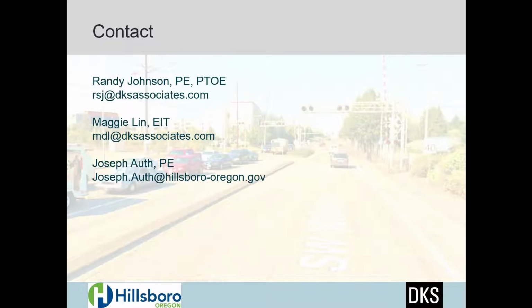So we run each of the 50 runs, and then there are a few key parameters that we looked at. Vehicle travel time was probably one of the primary indicators, but also checking for any latent demand. We don't want to choose a run that's completely blowing out the simulation, because of the random variation of the distributions, with a triple back-to-back event that we really don't see in the field. So really it's identifying the spread of the distribution on the travel time, and then there's a threshold: once it gets above 7 minutes or so, you know it's going to be in that super queue condition.